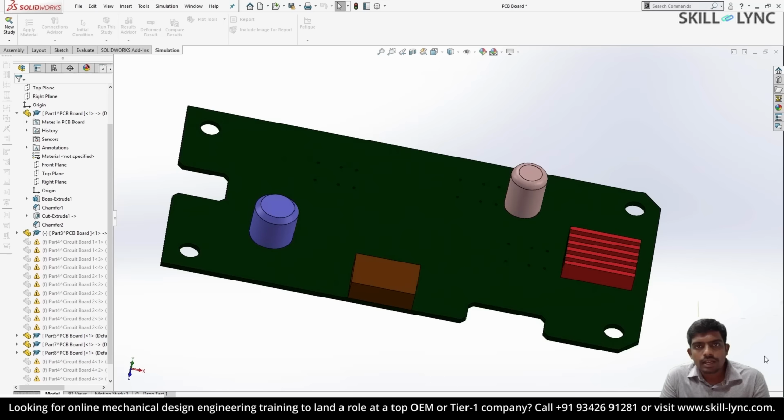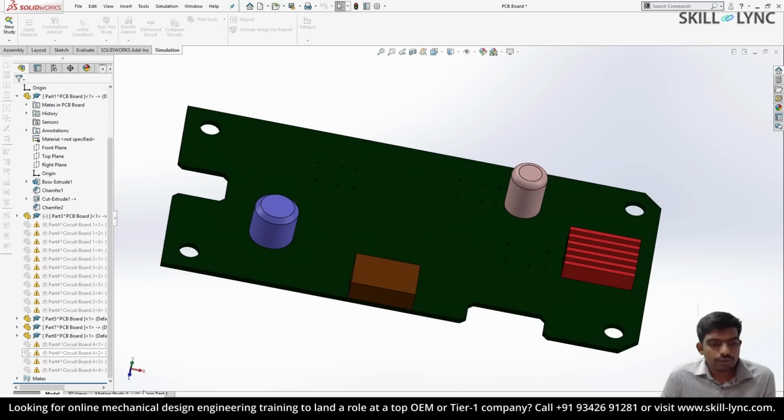Hence, when this electrical appliance drops, we need to make sure that the soldering that holds the electrical components to the PCB doesn't fail immediately after dropping it. To validate such cases, we perform drop tests on the PCB board and understand the stresses that will be developed while dropping it. Let's proceed with the simulation.